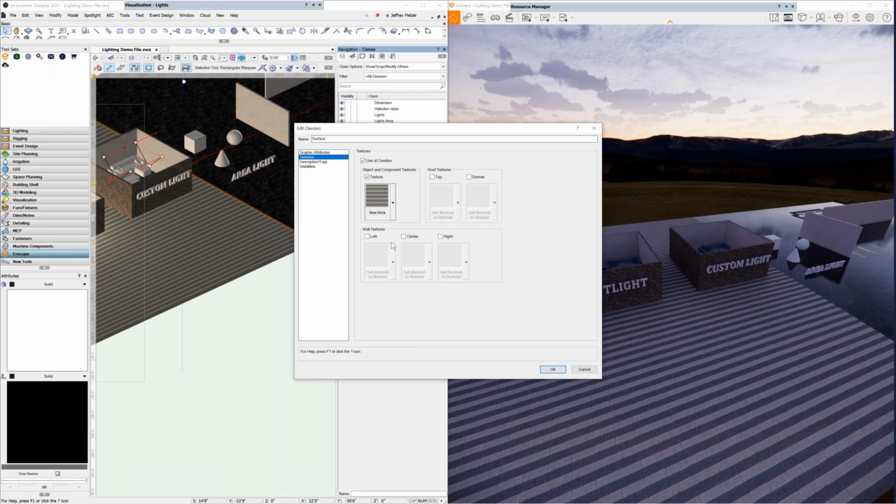There are a few other things that have some uniqueness to them with how materials are taken from them and placed. One of those being walls. So you can actually put in your textures here on the classes, a different material per side of the wall and areas of that. It would automatically take from this class versus doing each one independently. That can speed up a lot of things for you when you're working with projects with all kinds of walls and things. Roofs work the same way. You could do that.